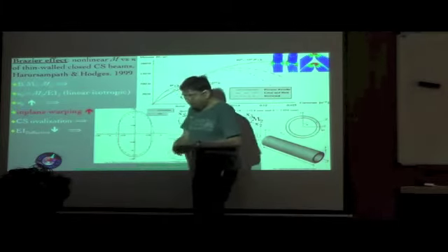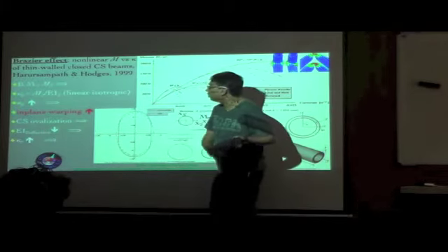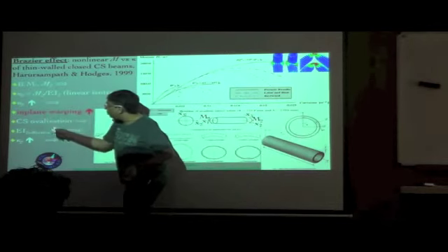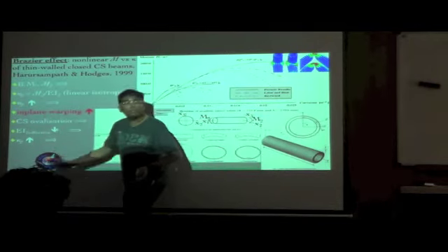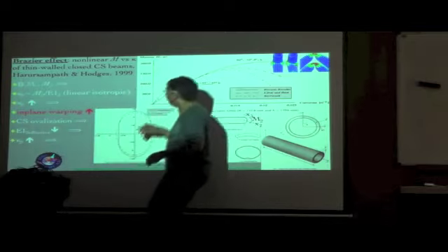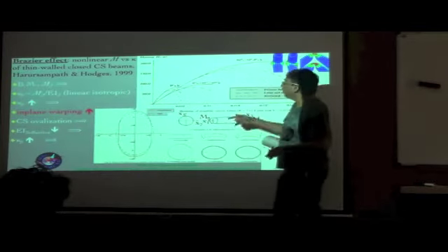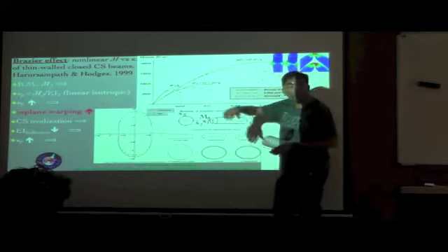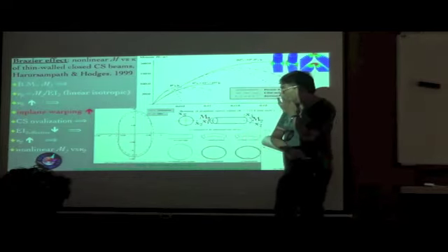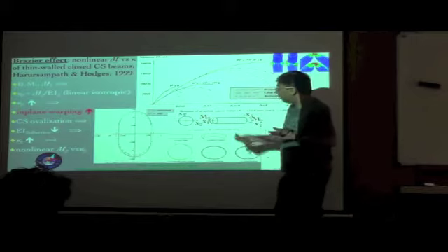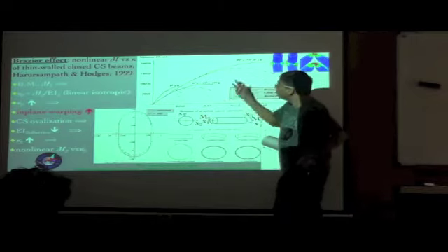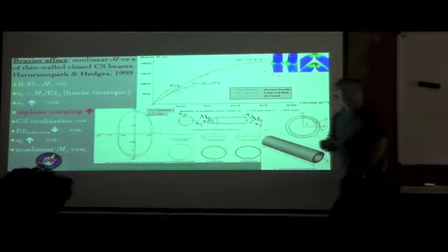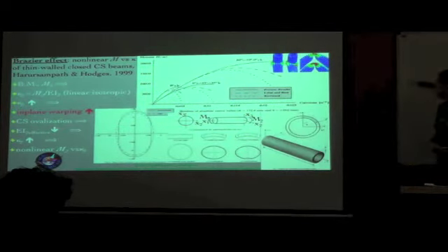And that in turn means that your bending curvature is going to increase further. Already it's the increase in curvature which caused this, and this in turn causes a further increase in curvature, and this kind of a loop eventually reaches a state where the curvature cannot be controlled, and that's the situation where you end up with the limit moment instability. But much before that also you basically see there's a nonlinear behavior between the bending moment and the curvature.